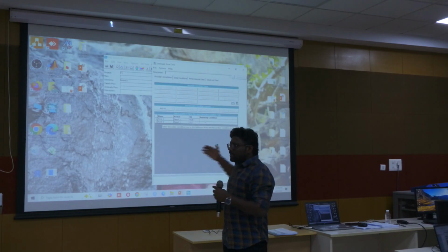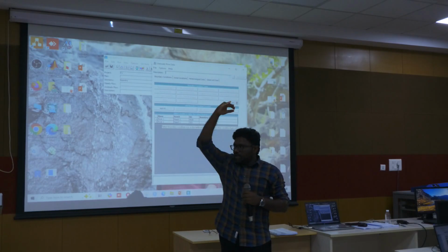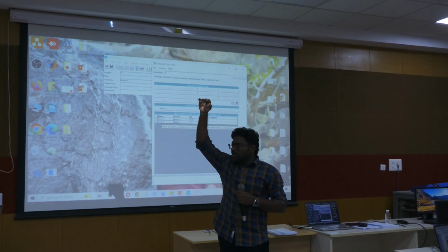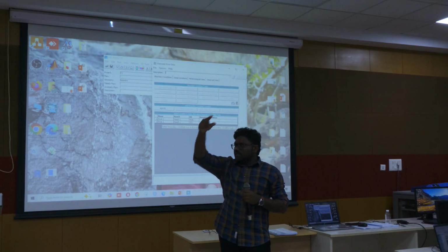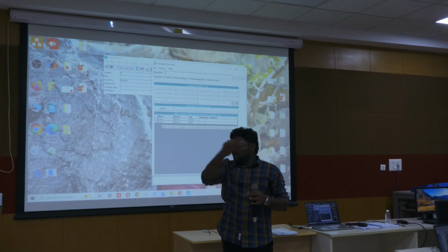Like that, it will go from downstream to upstream. At the upstream we have the Q value. If that Q is matching, then whatever depth you identified at the downstream is correct. Otherwise, it will iterate until then, identifying the depth value at each and every cross section.